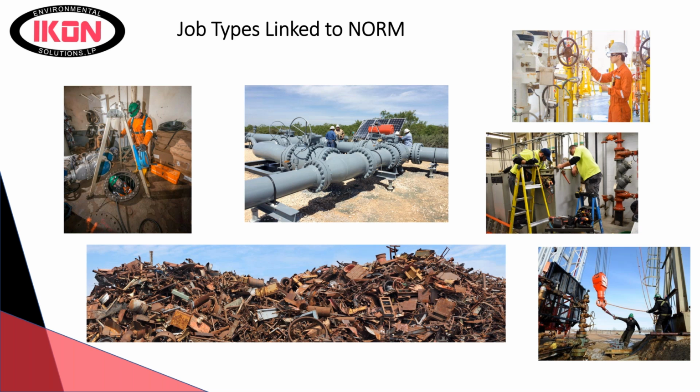Yeah, change in flow is what I usually tell people. Where you have a change in flow, if you have 2 miles of laminar pipe, it's usually fairly uniform. And all of a sudden you go from an 8-inch pipe through a reducing valve to a 4-inch pipe or a Y, you're going to see eddy currents in your flow, and you're going to have the deposits right there.